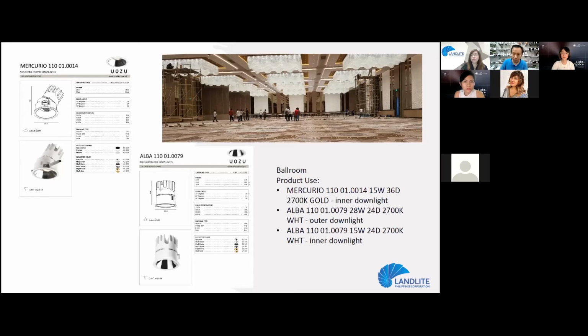Now, where did he use the 15 watts? He used it here on the side. Okay? On the side. By the way, of all the places, lahat ginamit niya is 3,000K except for the ballroom. 2,700K ang ginamit niya sa ballroom. Okay? To make it more elegant and warmer. So, these are the fixture that he used for the ballroom.